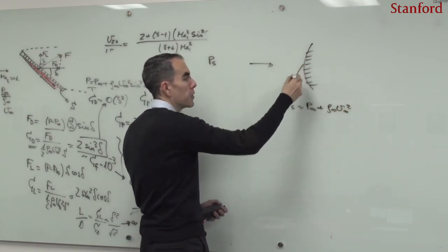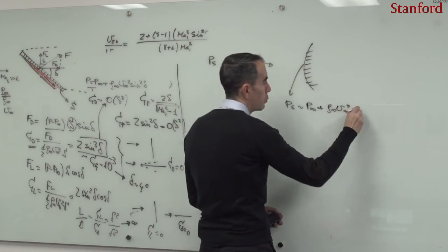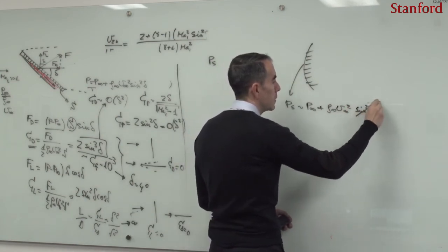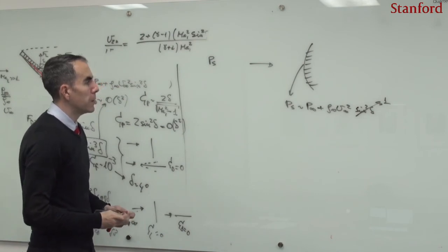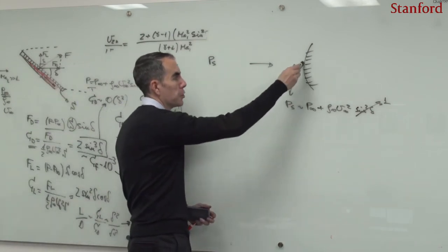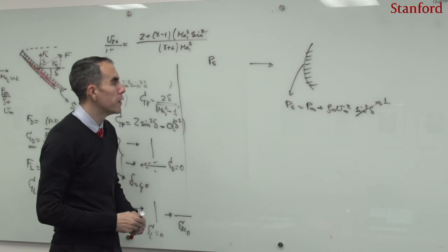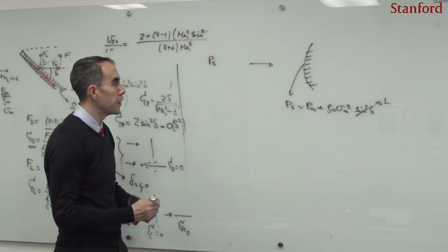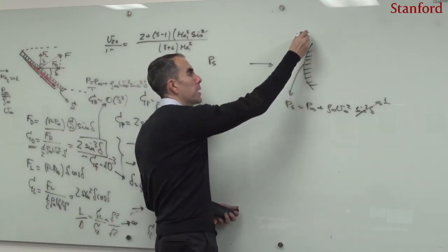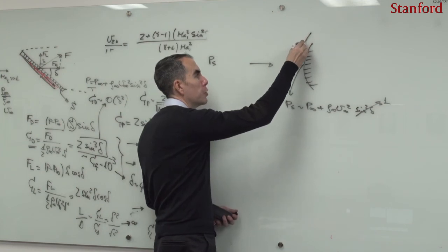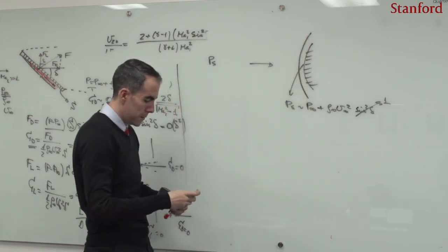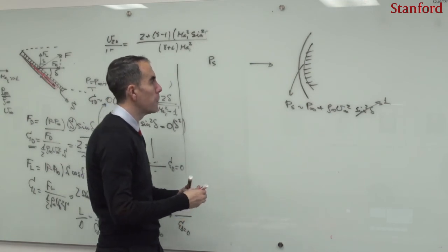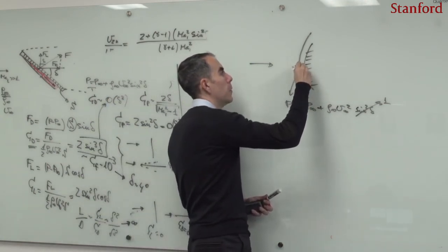Here the inclination angle is 90 degrees, so if I were to put here the sine squared of delta, this number would be 1. And then he realized that this surface pressure predicted by the Newtonian theory is actually higher than the pressure that one would obtain if one were to look at the problem of a bow shock around this blunt body, and then one would wonder what is this post-shock